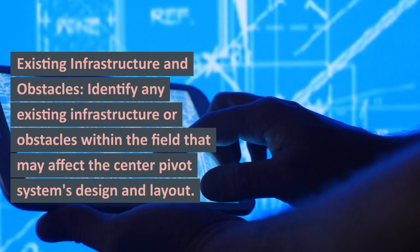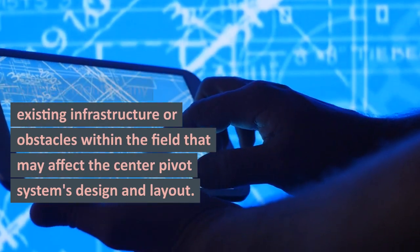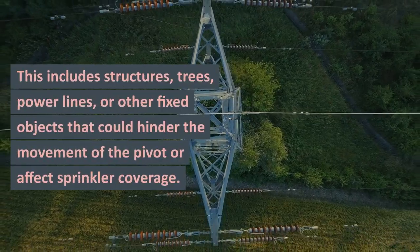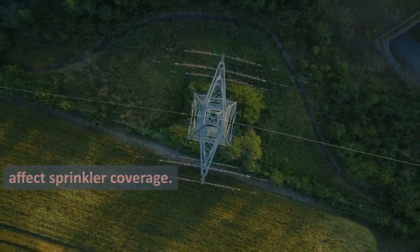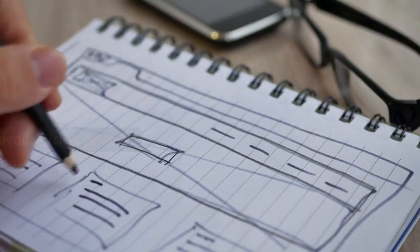Existing infrastructure and obstacles. Identify any existing infrastructure or obstacles within the field that may affect the center pivot system's design and layout. This includes structures, trees, power lines, or other fixed objects that could hinder the movement of the pivot or affect sprinkler coverage. Plan the layout accordingly to avoid such obstacles.